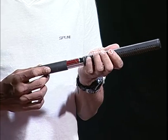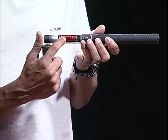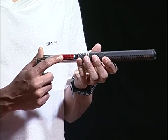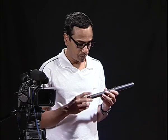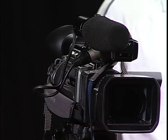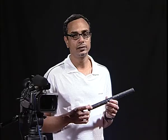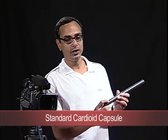So it will require additional power supply, which can be given in this particular case by a 1.5 volt standard AA size cell. Now, if we don't have the battery, this microphone is designed to be supplied with phantom power. And normally a camera like this will have an additional facility to provide the phantom power to a microphone like this. Now, this microphone has a standard cardioid capsule inside,